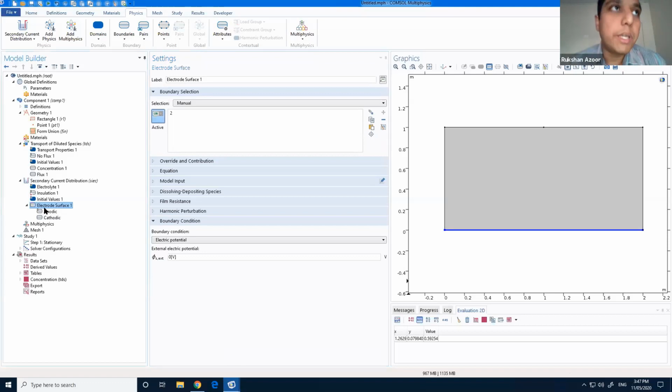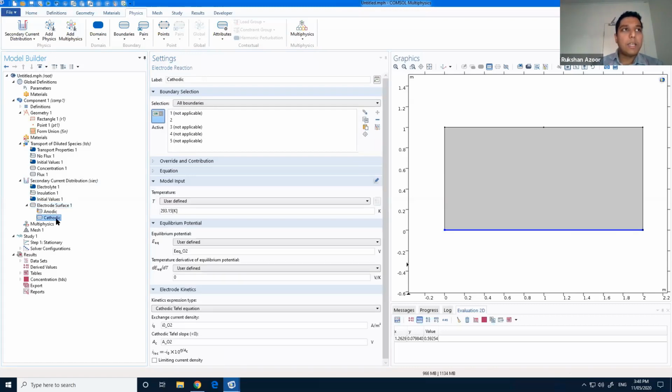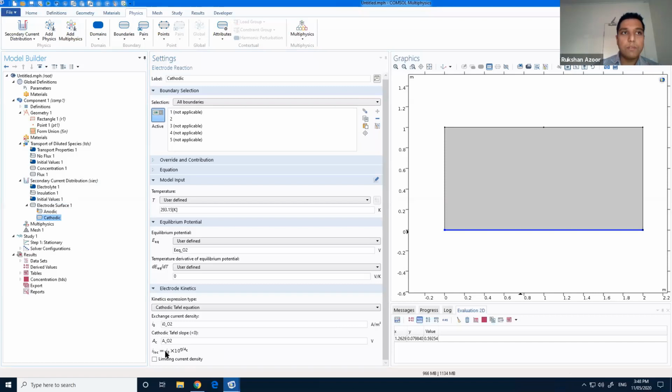So let's just recap what we are doing here. Now we are doing the corrosion simulation, and corrosion is going to give us the corrosion rate at this interface. Of those corrosion reactions, as I mentioned earlier, the cathodic reaction is going to consume oxygen, which means it's going to result in a flux. Technically, it's resulting in a corrosion current, which can be converted to a flux. Therefore, this corrosion current or the corrosion rate will also depend on the availability of oxygen, just like our previous case. Because if there's no oxygen at this level, there can't be any reaction, and therefore there can't be any flux. So we need to multiply this with our same early trick, C by C ref.